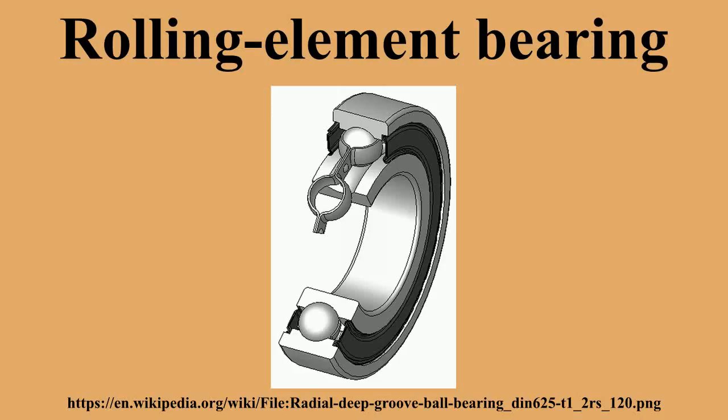Gear bearings could be used, for example, as efficient rotary suspension, or kinematically simplified planetary gear mechanism in measuring instruments and watches. Tapered roller bearings use conical rollers that run on conical races. Most roller bearings only take radial or axial loads, but tapered roller bearings support both radial and axial loads, and generally can carry higher loads than ball bearings due to greater contact area. Tapered roller bearings are used, for example, as the wheel bearings of most wheeled land vehicles.